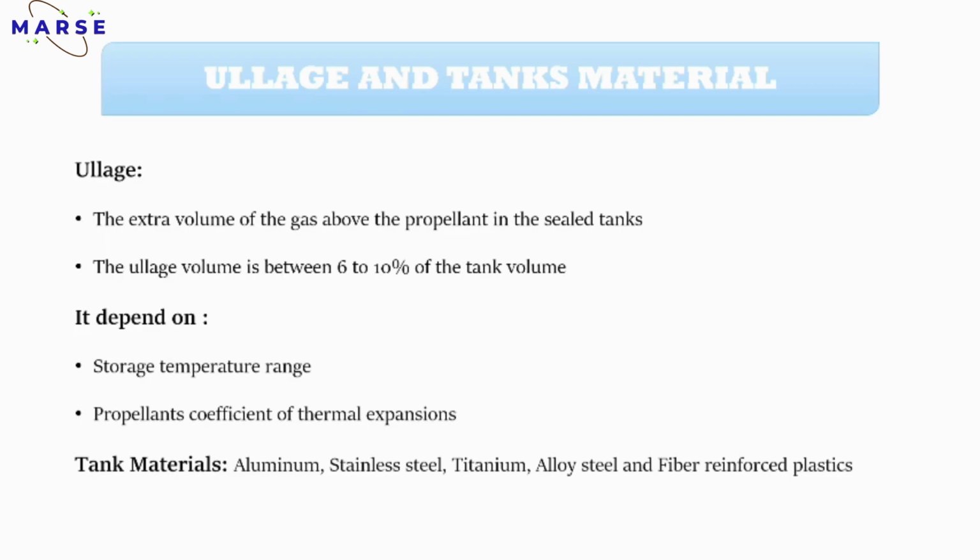It depends on the storage temperature range and the propellant coefficient of thermal expansion. So these factors affect the ullage part. When you are designing the ullage volume, you first have to consider the storage temperature range and the coefficient of thermal expansion. Then and only then can you design it.